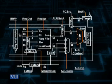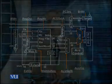As you can see from the diagram, the 4 values which may be provided to the ALU as the second operand are: the topmost value, equal to 4, which is used to find the next address in the program counter. If you recall from our previous discussion, on the completion of the fetch of an instruction, the program counter is to be incremented by 4.